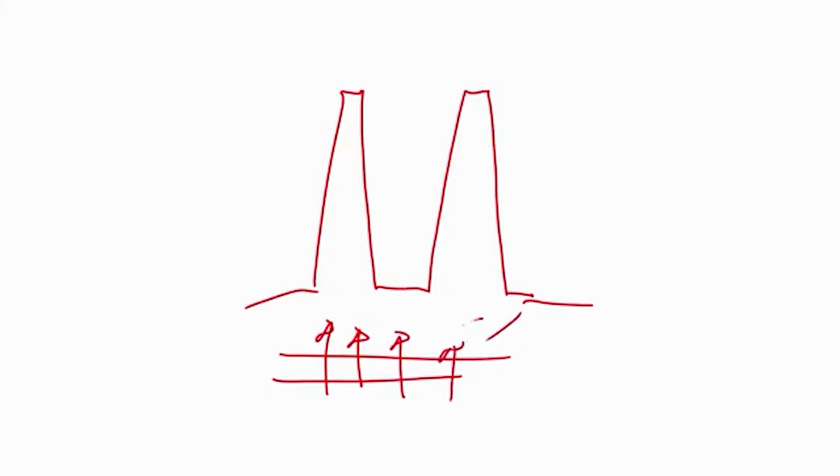So, we have enough fluid passing there, and from here, let us say this is the base plate, heat flux comes here, this whole thing is taken by this section and slowly heat starts flowing here. If the base is typically at 80 degrees centigrade, the tip may be only about 70 degrees centigrade instead of 30 or 40 degrees.